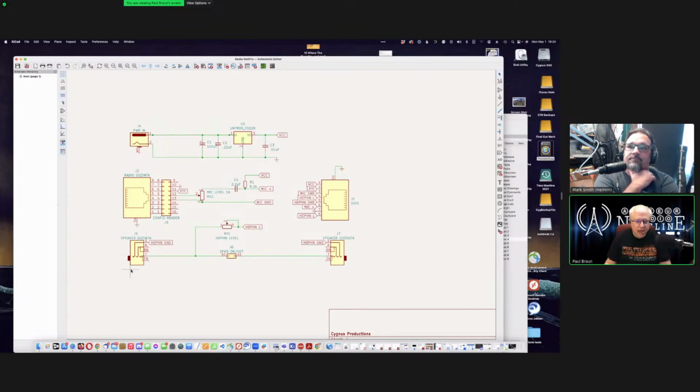This is the input jack for the speaker audio. This is because I don't want to eliminate the speaker, because on the Yaesu, I use mine with my control head mounted remotely on a little bitty tripod. The headphone jack is on that thing. So in order to get that headphone audio into the OHIS system and into my headphones, I need to run it from there all the way back down to the rack and then back out. Or I can use the speaker jack on the back of the radio, which will do the same thing, except it's pumping out speaker level audio.